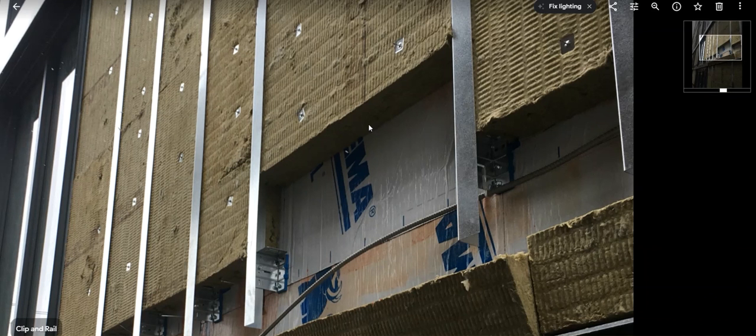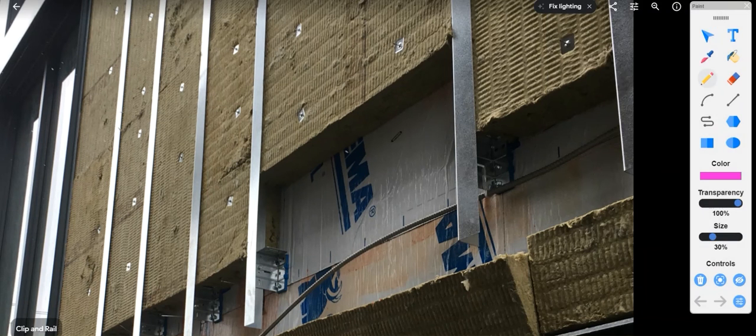But again, if this was 150 millimeters of insulation, then this part of the wall here would essentially meet that R27 or RSI 4.65, pretty close anyways. But once you consider the thermal transmittance through these clips, and they're going to be every so often, so there'll be one about there or whatever, then you're not going to be meeting that RSI 4.65.